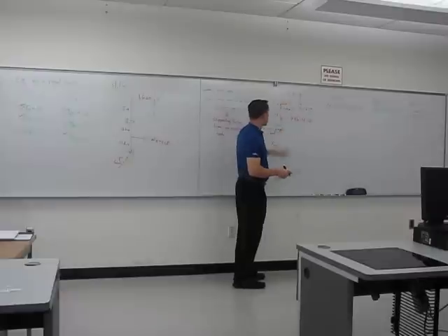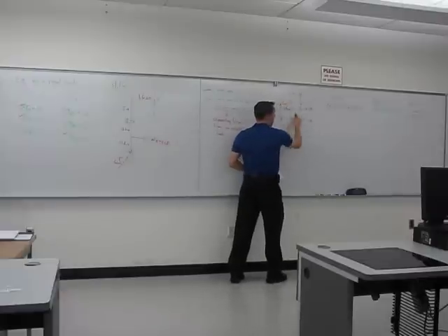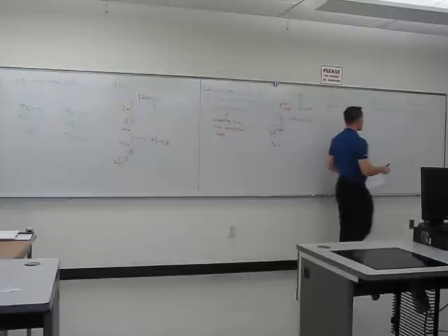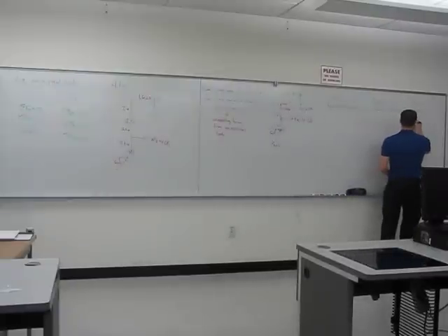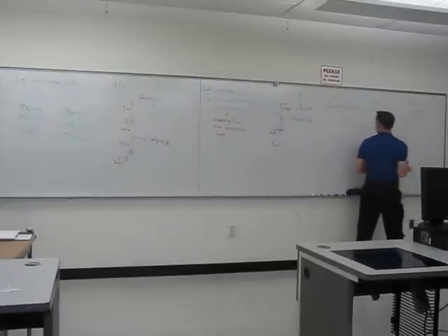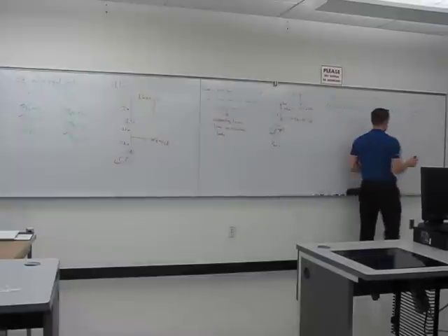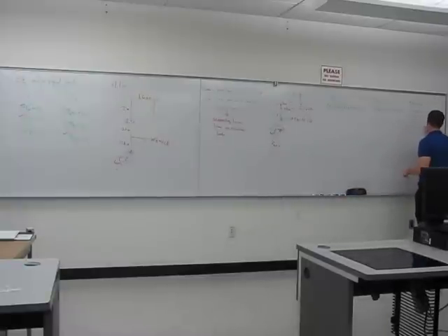D, if you hold the point C fixed and you pull down on D, that's going to spin you clockwise. So this one's going to be a minus, and you're going to have Fd times, you see the distance between C and the line of action for D is 1.6. And that's equal to 0.